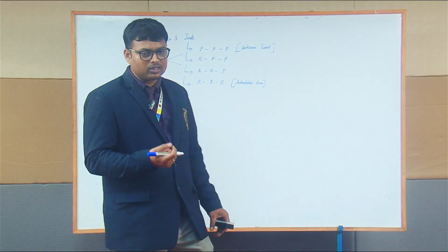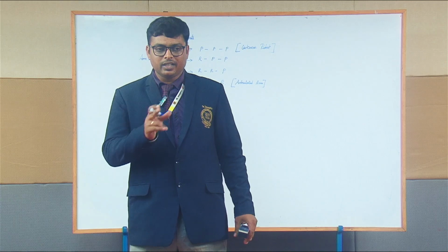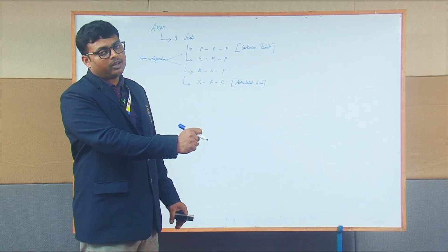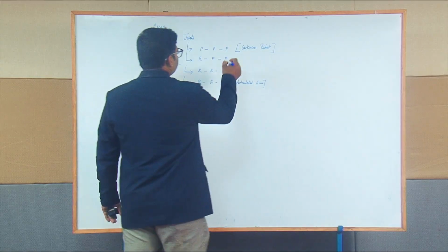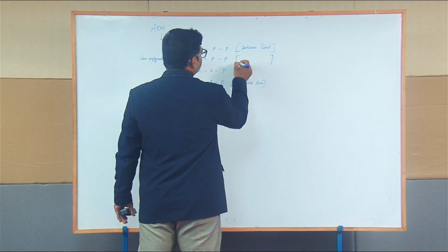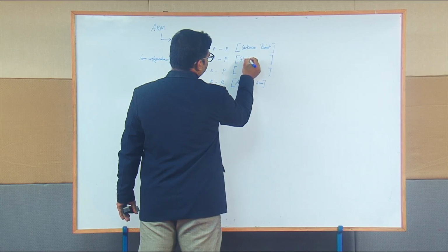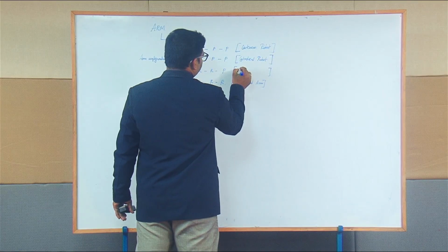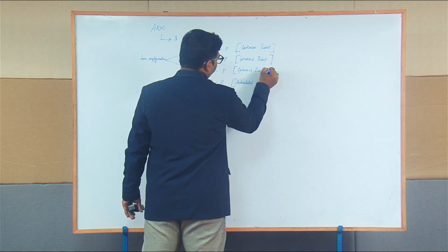So the beauty of having the joints as rotary is you can perform a linear action even though the 3 joints are rotatable. So performing a linear movement with the help of 3 rotatable joints is the beauty behind articulated arm. So the second one is called cylindrical robot. The third one is called spherical robot, or we can say it as telescopic configuration.